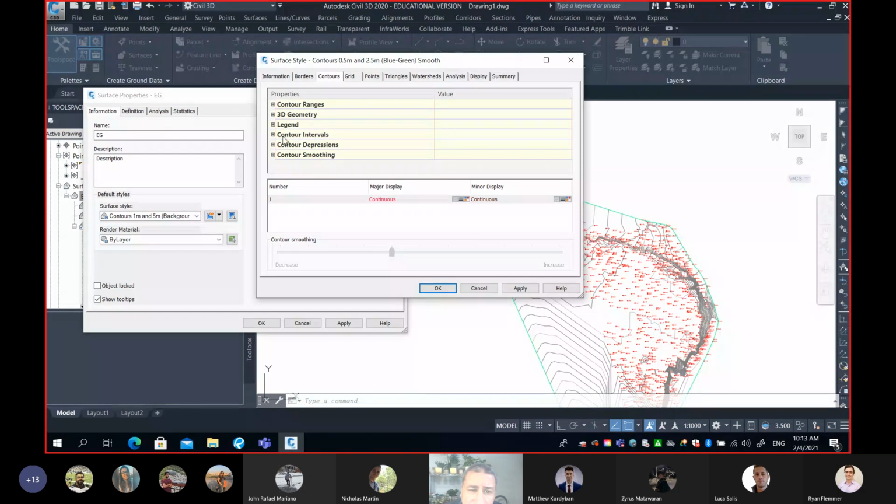And it's very clear. It says here contour interval. All you have to do is you click on this plus sign. It simply shows you what are the current interval for the major and minor. You can see all you have to do is you come here and then you edit this number point 1, 2, you change it to point 0.5. And the good news is if you change your cursor, you can see automatically the major contour went to 2.5.